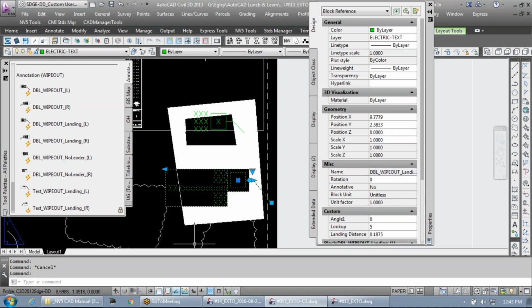If you want one to mirror, let's say, and be on the other side, do not mirror this, all right? This has been happening inside the group, and it's a practice that has to stop. Do not mirror these. There's a reason why they're developed left and right. It deals with the text justification, all right? So it's very important that you don't just mirror this. Your text isn't going to be all lined up correctly. So instead, bring in the right block.